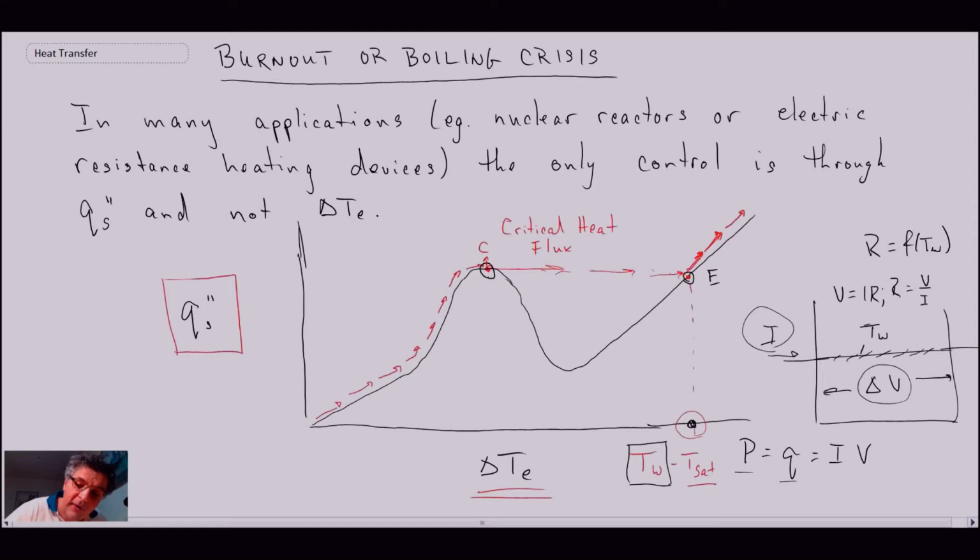Now you might be wondering, how was the rest of the boiling curve determined between the critical heat flux point and the Leidenfrost point down here, which we call D? Well, the way that you do that is a temperature controlled experiment. An example is if you have a pipe and you put a vapor in it that's going through a phase change. If you change the pressure in this pipe, you can vary the saturation pressure. That would be what you would do for your wire.